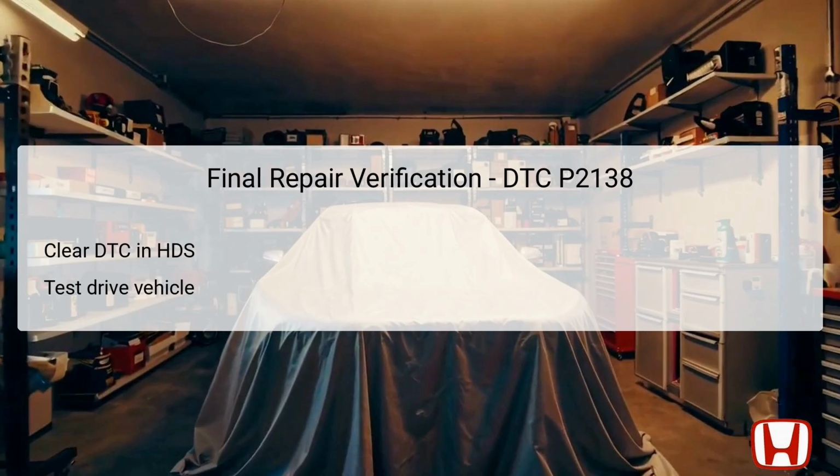Following this action, take the vehicle out for a test drive, observing its performance during various accelerations. During this test, pay close attention to the responsiveness of the accelerator pedal. Gauge any unusual behaviors and confirm that the check engine light remains off. Successful completion of this step confirms the resolution of the issue and the reliability of the repairs made.